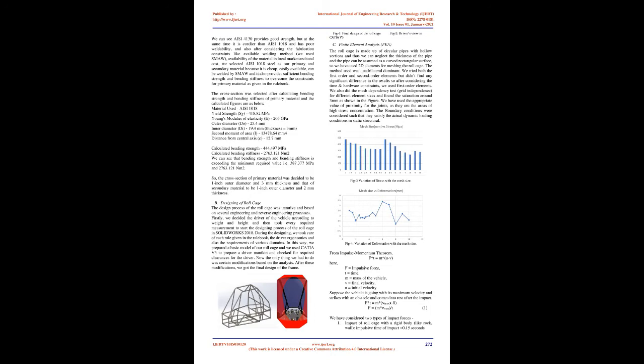4. Frame. The frame is a structure made up of metal tubes whose main objective is to ensure the safety of the driver and carry different components of the vehicle such as powertrain, steering and suspension, etc. The design process of the frame can be divided into 4 steps. 1. Material and cross-section selection. 2. Designing the roll cage according to the rule book. 3. Analysis of the roll cage with calculated boundary conditions. 4. Ergonomics check using PVC pipes.